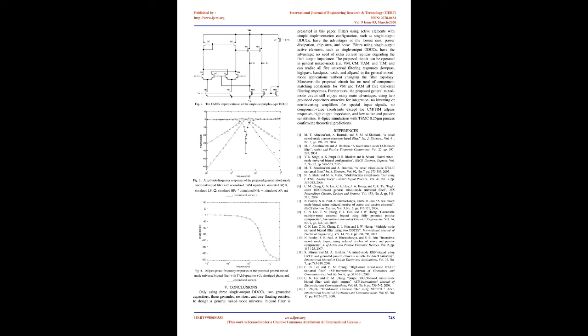They can be approximated by the first-order low-pass functions [33, 42, 45 to 50]. For frequencies much less than the corner frequencies of the DDCC, all α(s) and SS(s) are real quantities of magnitude slightly less than 1 [33, 42, 45 to 50].